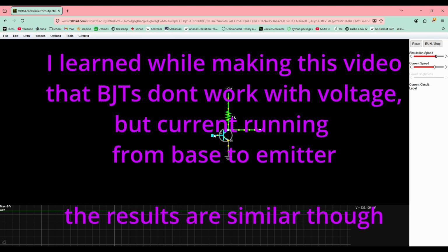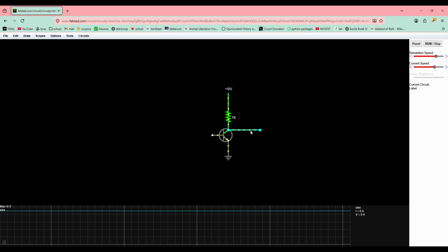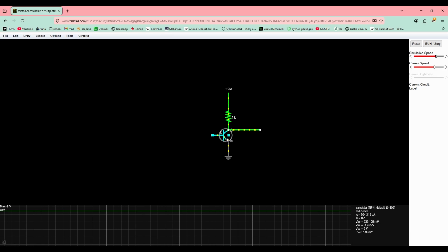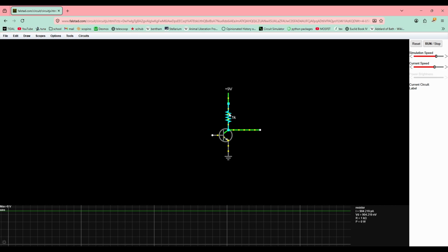voltage at the base. We are measuring the voltage at this wire, and since there is no current running through here, it's at 9 volt. Because you can see this transistor as an infinite resistor. So with an infinite resistor here, if this would be a voltage divider, 1 is 0% of infinite. So we are exactly at 9 volt.